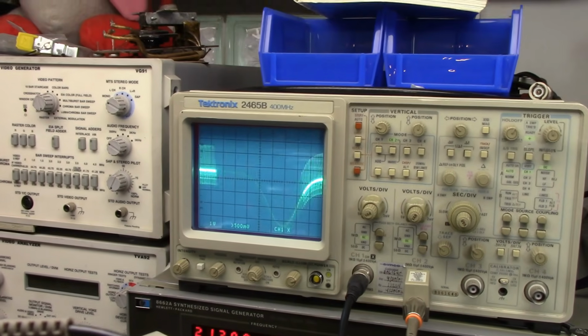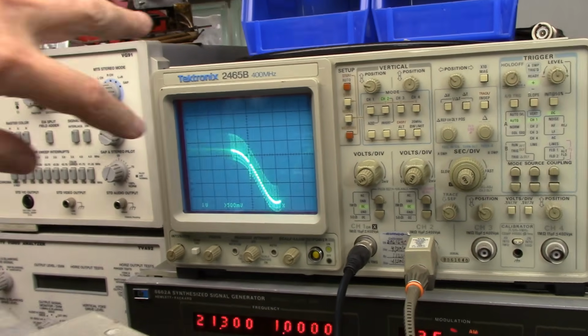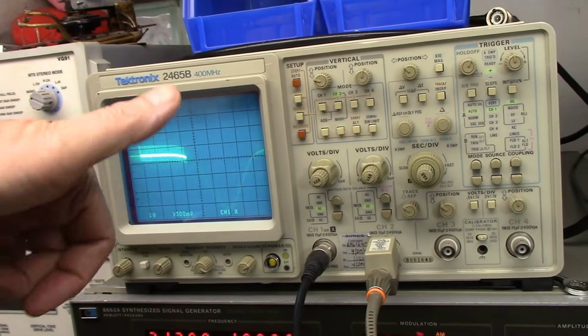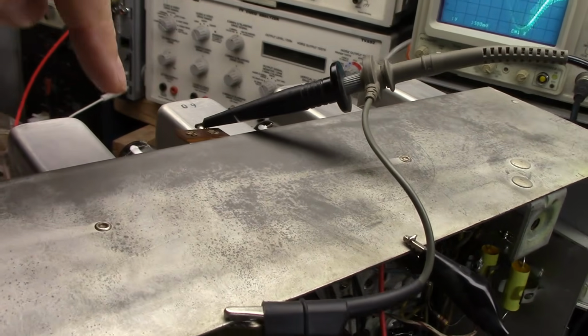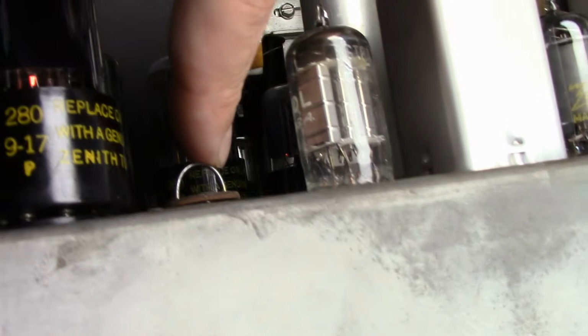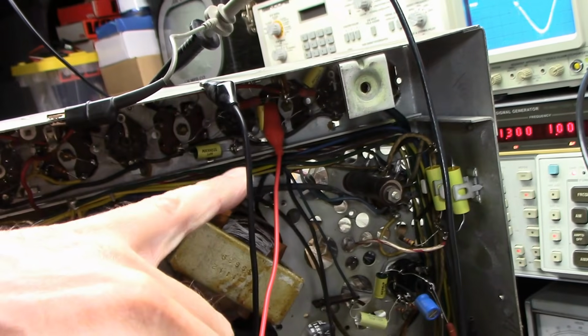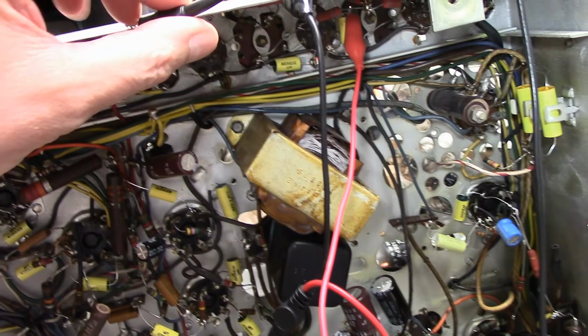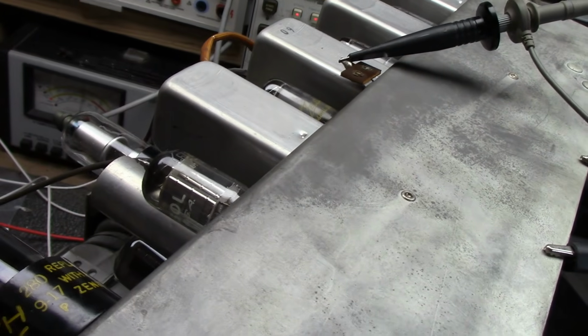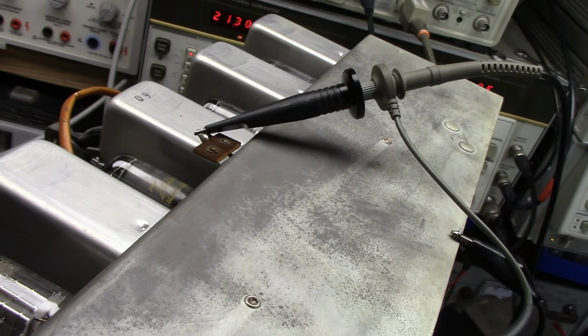Okay, now we're getting to what I really wanted to see, which was the IF response, and sure enough it's way off. So again, 21.3 is in the middle. We are peaking way over here, and then you shift it over to the left. Just like with the other alignment steps, they make things convenient for you. For this stage, you clip the scope right to this access point here. For the earlier step, I was clipping to this point over here. So you can almost do it all from the top of the chassis, except you need to inject the signals on the bottom of the chassis. So maybe they had a test jig so they could do injection from the top at the factory. I'm not quite sure, but anyways, at least there are some conveniences they added.